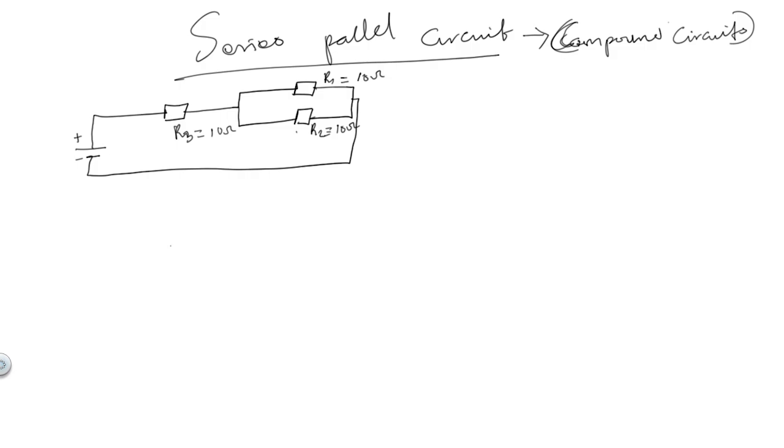The formulas required for solving current, voltage, and resistance problems have already been defined before. So to solve a series parallel circuit, we reduce the compound circuit to its simplest form. And how do we do that? How do we reduce it from complex to a simple form? We reduce it in this way. First, we use the formula to determine the total resistance in parallel.